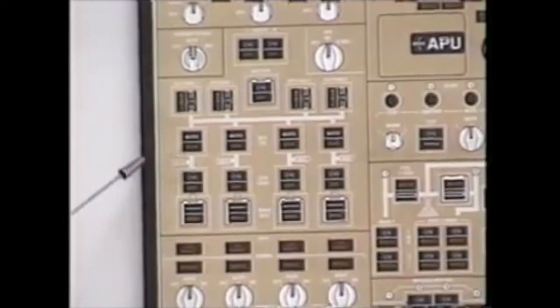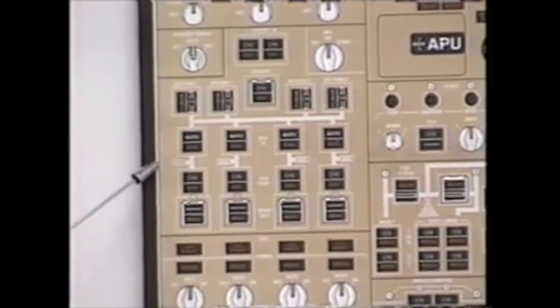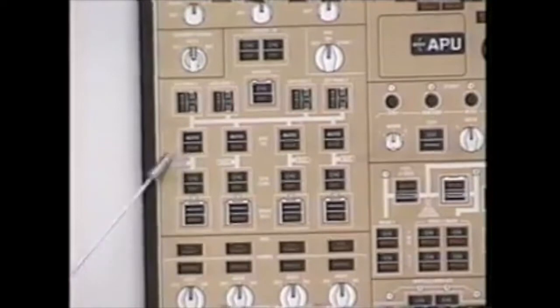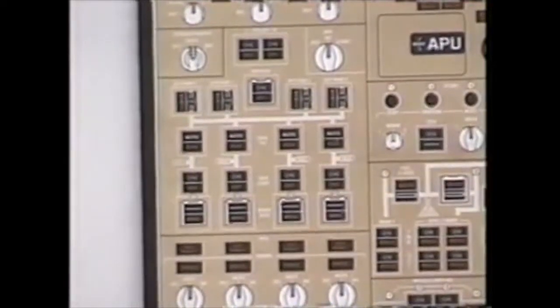The service bus works anytime AC bus 1 is powered, such as in flight. So to help you distinguish between the ground handling bus and the ground service bus, I dropped the word ground from here. So on your service bus, the important items are your 2 battery chargers. Also your stab fueling, and a number 2 aft boost pump for APU operation on the ground. The service bus, again, is normally powered by AC bus 1. Anytime AC bus 1 is powered, it will power your service bus, whether you want it or not.